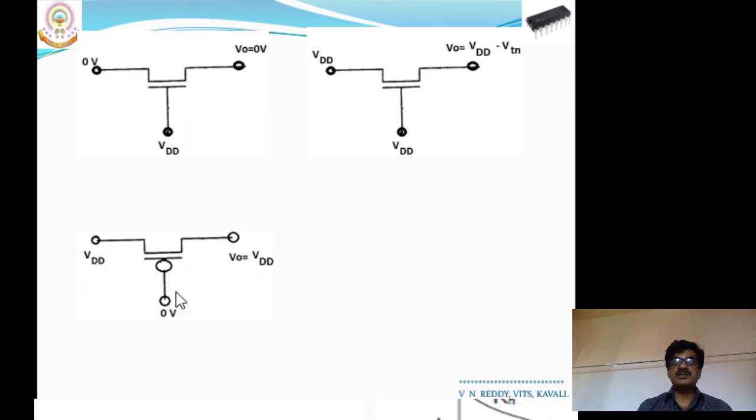That is, with reference to logical high, the pass transistor shows perfect transmission. But in case of logical low transmission, this is the logical low value applied at one end, but at the other end we can't get that 0 value. It is always equal to the threshold voltage value, that is VTP.